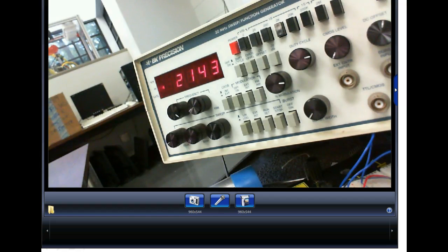So what we're doing, guys, hopefully we're going to go ahead and go to lab. We're working on our unregulated power supplies. So right now we're just trying to get the transformer on the trainer, right? We're using the transformer on the trainer. We're doing half wave. And then we're putting the filter capacitor across there.